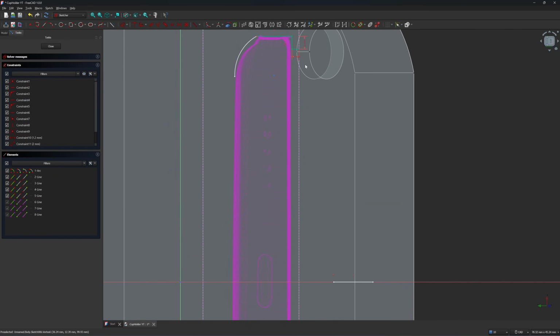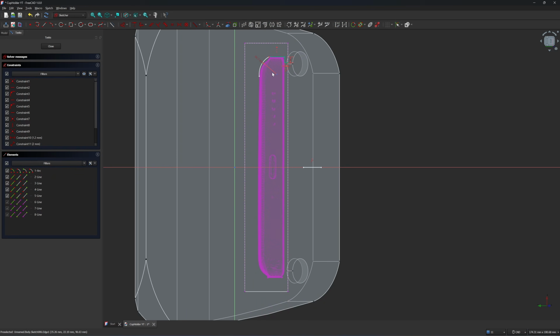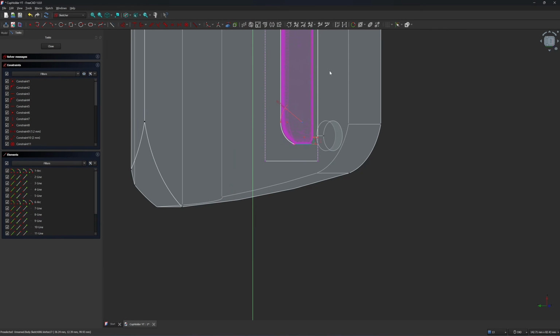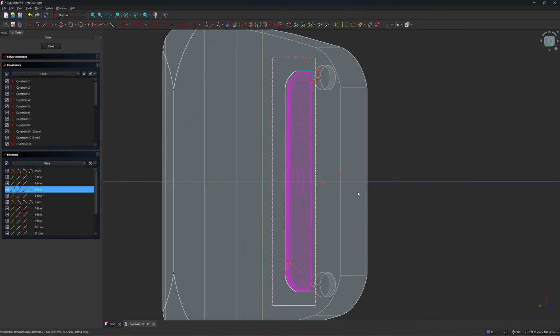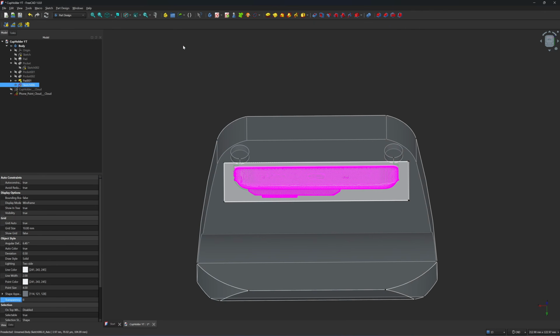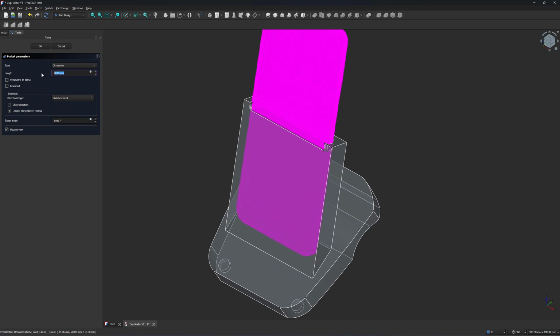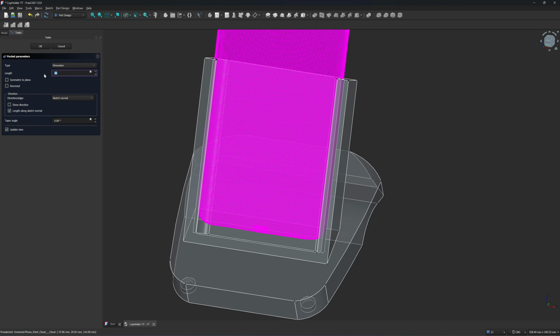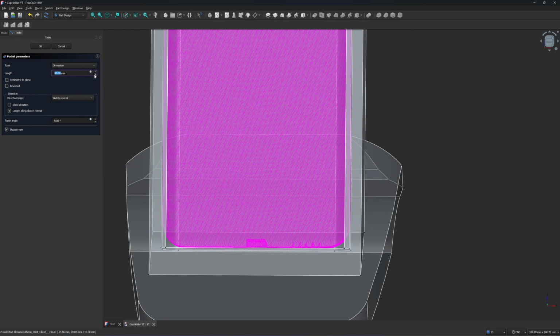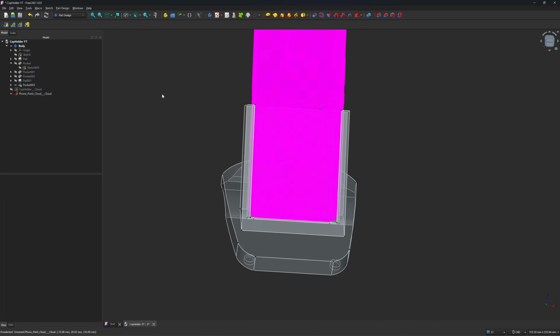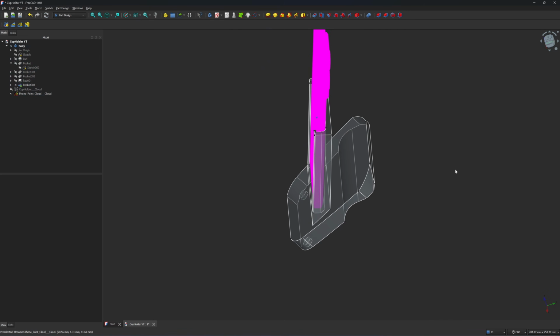Then I'm going to 11 millimeters and 6.7. Okay, I will mirror this to the other side. Mirror command, mirror line. This should be a closed loop, right? Let me delete the mirror line. Close. Okay, this could be a closed loop. Okay, it's closed. 90. Too much. 85. You can use this until it touches the point cloud. Yeah, 85 is okay. Okay, now we have a profile for the phone.